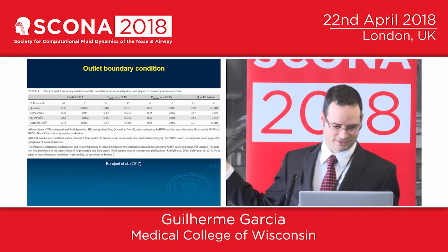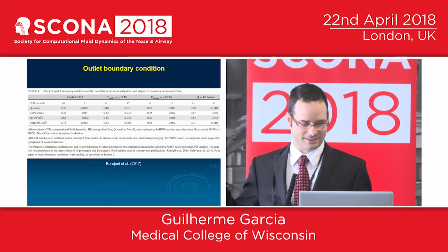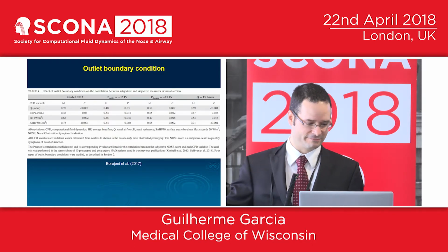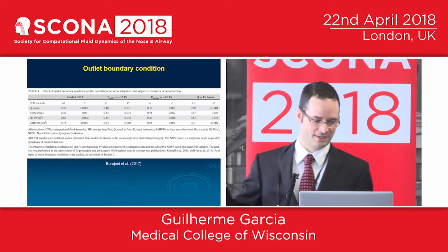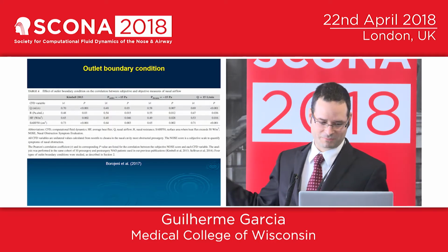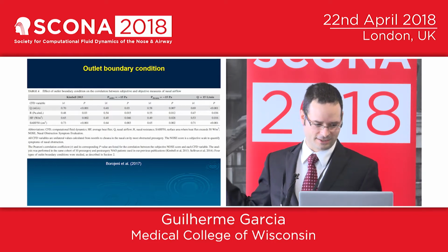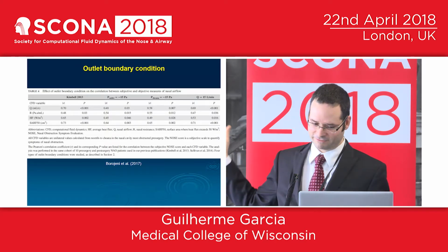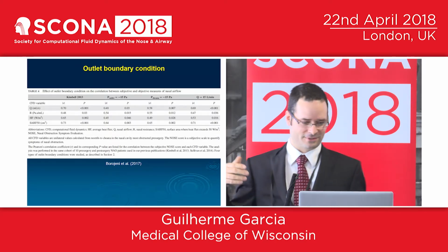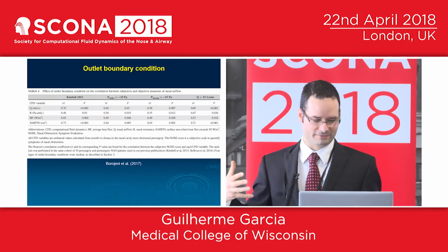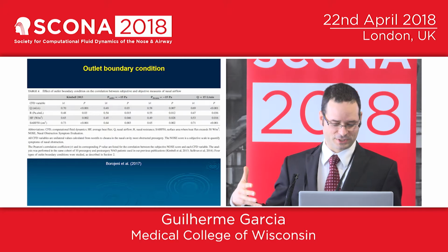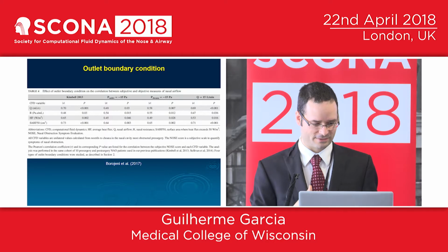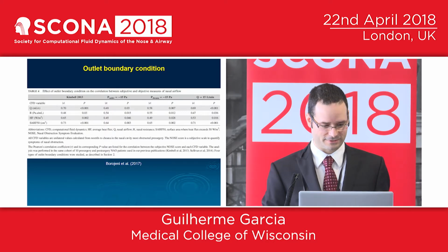flow rate and nasal resistance. And what we found was that the best correlation between the patient-specific subjective measures of nasal obstruction and the CFD variables was obtained by setting a constant flow rate, either the patient-specific flow rate in the Kimball 2013 paper or the 15 liter per minute flow rate. Because with a constant flow rate you adjust the pressure, so the pressure at the nasopharynx or the configuration of the nasopharynx doesn't play as much of a role.